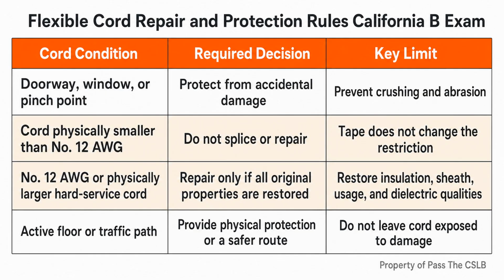Imagine a contractor who finds a damaged light-duty cord 10 minutes before a concrete placement. The schedule pressure is real, but it does not change the cord category. Wrapping the damage and putting the cord back under load converts a visible defect into a hidden defect. The safer field decision is to stop using that cord and provide compliant equipment rather than turn the pour into the reason for accepting an unapproved repair.